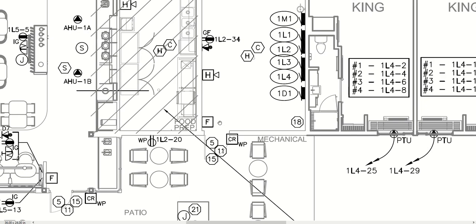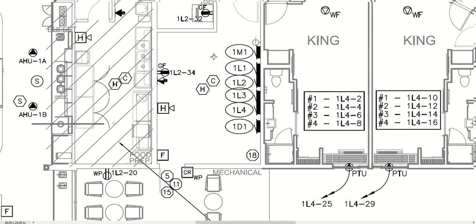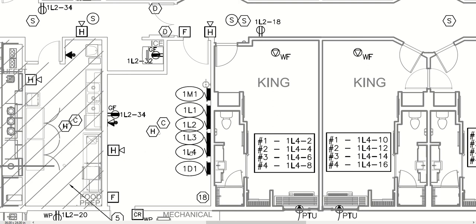And here's another electrical room that's on this floor. It's actually the only other one. This is a combination electrical and mechanical room, which is pretty common. And so they've got some major mechanical equipment in here, and then they leave us space over on this wall. We can put electrical panels, and that's okay as long as they maintain the clearances. To save space a little bit, they'll do that type of thing.